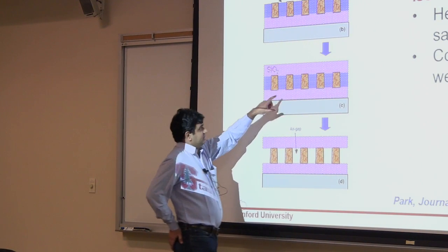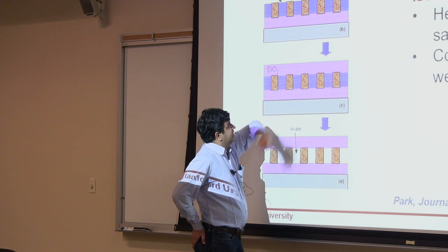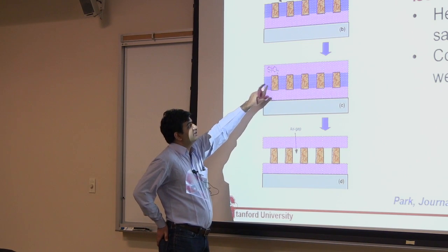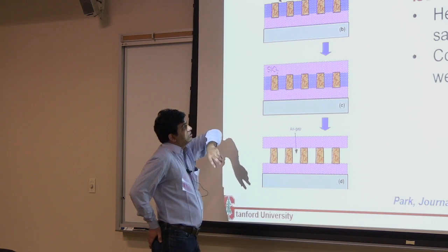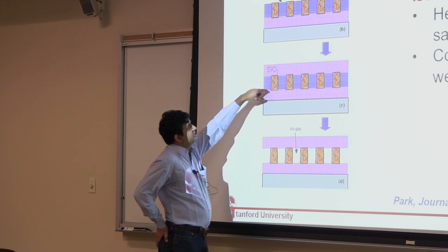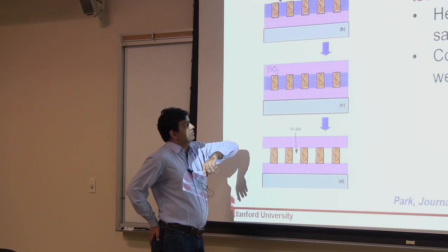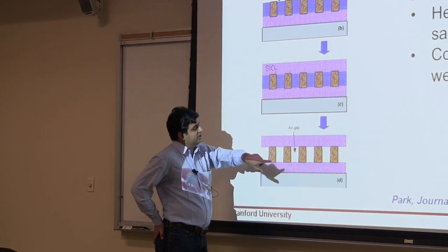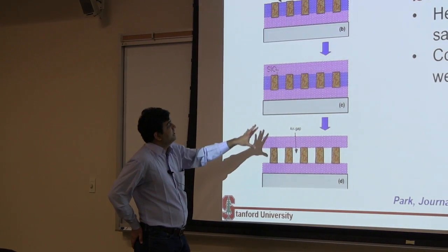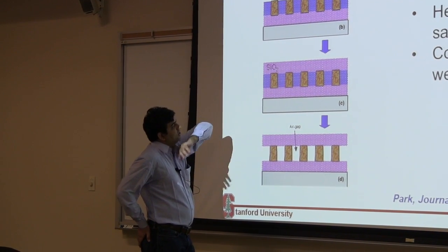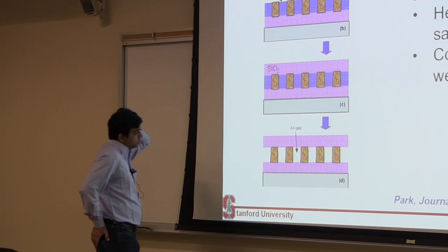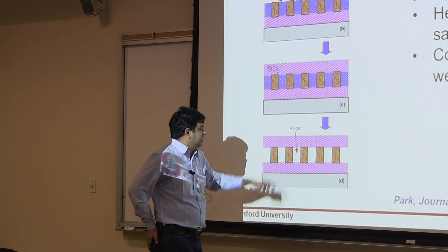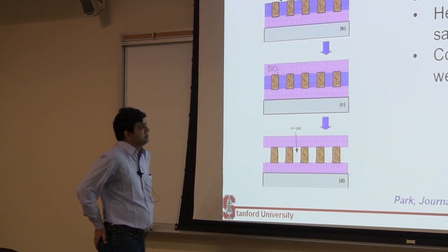So you can make pores into this dielectric, and then you can do either of two things. You can heat it up such that if this polymer has a lower evaporation temperature, it will just evaporate out of the pores. Or you can bring a chemical in through the pores, and then you can remove this polymer. So either way, you can evaporate your polymer out, or you can etch it out. And this is the way you get an air gap between these structures.